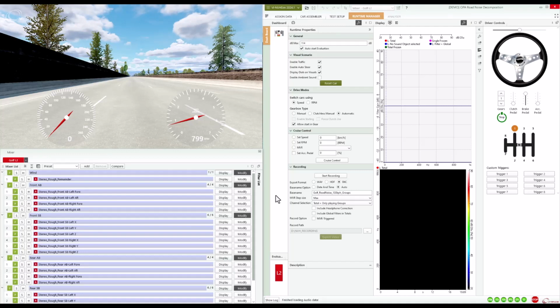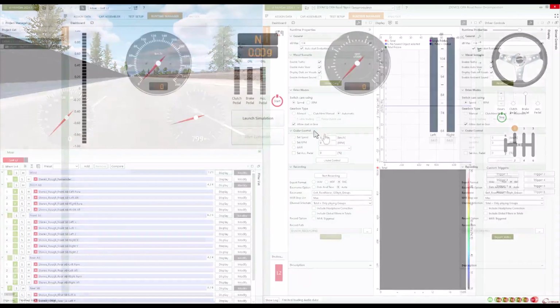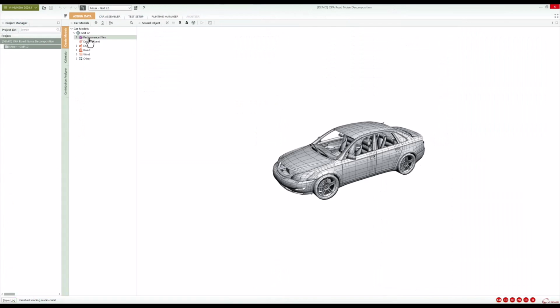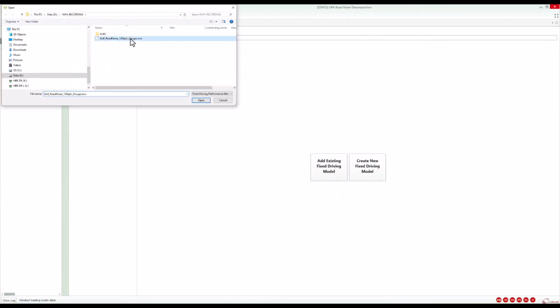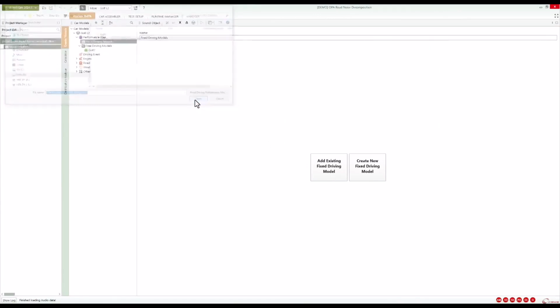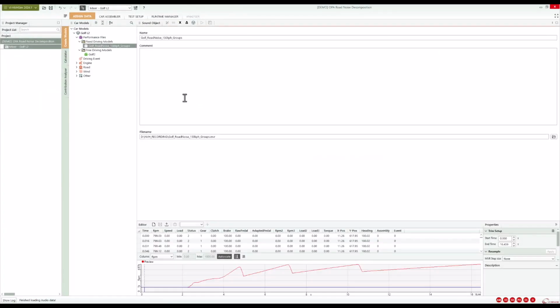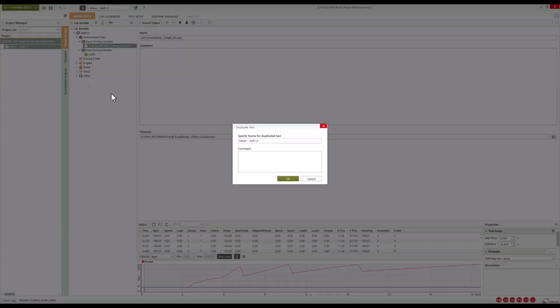One of the benefits of working in simulation is we can automate this process, improving the reliability and making sure we're always exercising exactly the same operating condition. It just makes us work a bit faster, more efficiently and more accurately. Through the recording that we made previously, we can configure a fixed driving test very easily. This allows us to exercise our model, but keep some of the operation of the vehicle in the responsibility of the simulator itself, offloading some of that to the software.